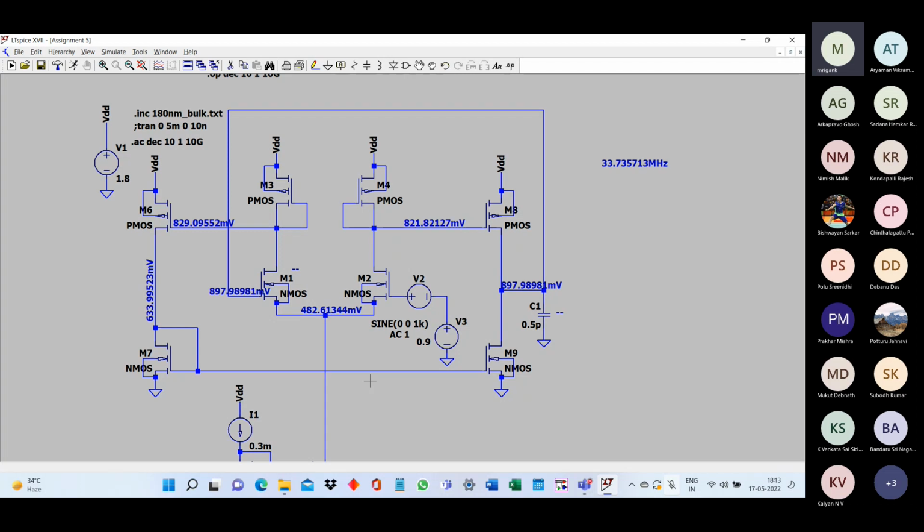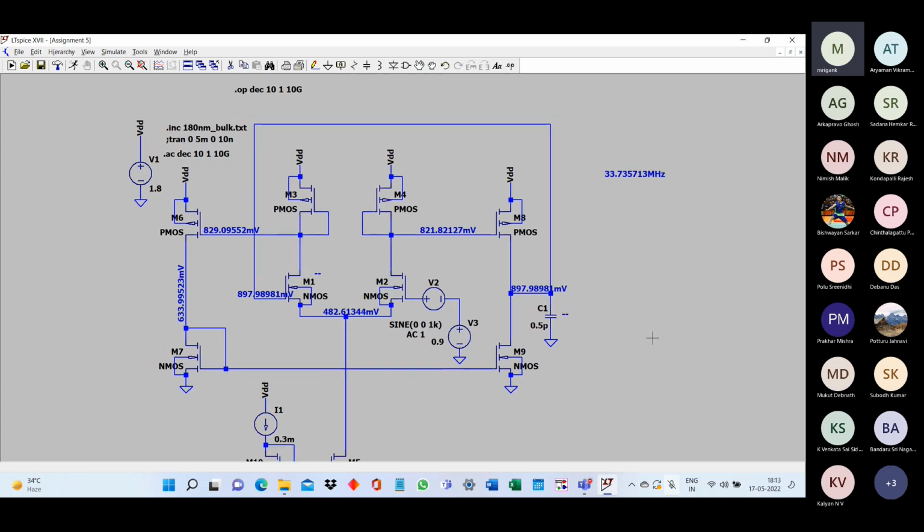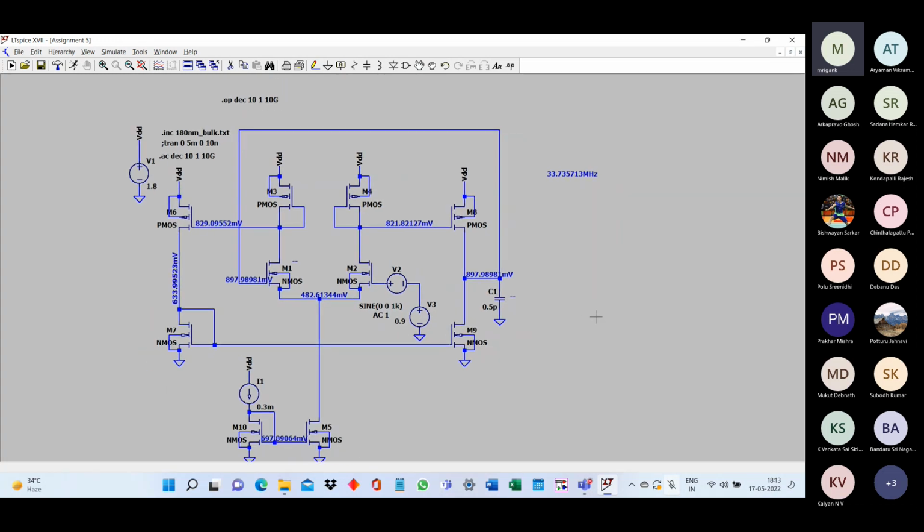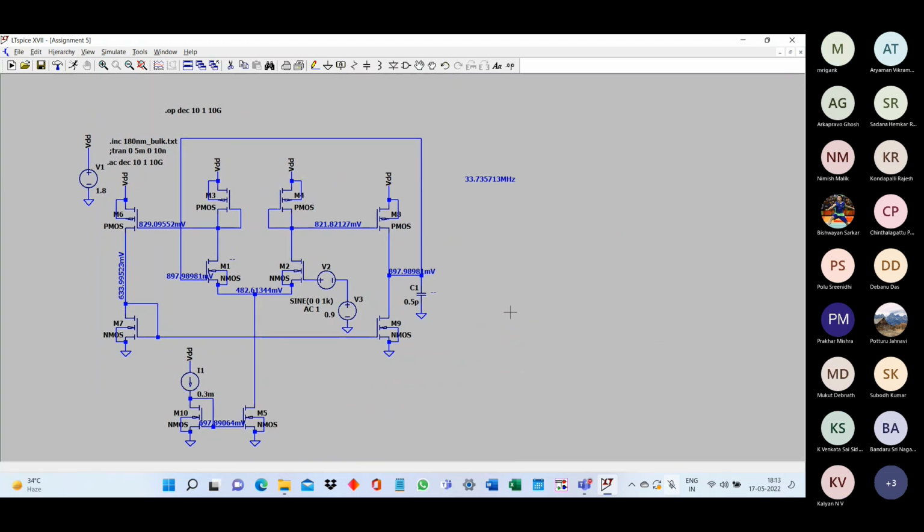Increase the small signal current, making sure that whatever current is produced by the first stage, GM1 VGS, is reaching the output stage, and increasing the RO of the output stage by increasing the channel length. That's all. In this case, if we had a current mirror load or a current source load at the first stage, the story would be different. There, we would not talk about just routing the current, because we would have good gain at the first stage itself.